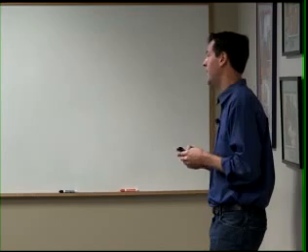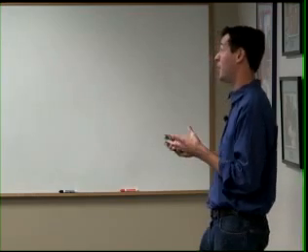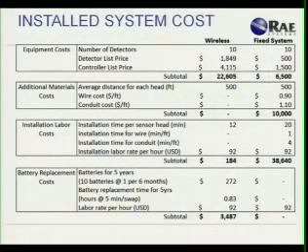Okay, then finally, there are battery replacement costs. On a wireless system, the batteries do have to be replaced. We're using an estimate of once every 6 months. The total cost for 5 years of batteries on a 10-point system is roughly $3,500, including the labor rate, including the batteries, including the cost of everything. So $3,500 over a 5-year span. Whereas on a fixed system, there's nothing. You have your hardwired power, it's there. You never have to replace batteries. There's no labor costs involved. So it's really a zero for a fixed system in terms of battery replacement costs.